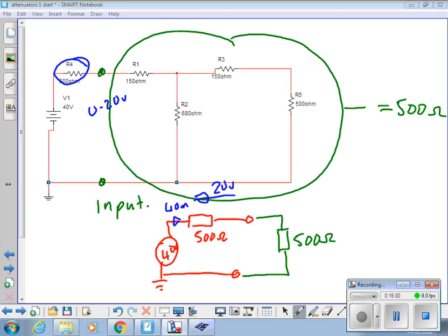So if that was a sensor and I connected it all up, open circuit, at top pressure, I'd get 40 volts out of it. Yeah, because the voltmeter is not going to draw a significant current, and therefore I'd measure 40 volts. But when I connected my 500 ohm to it, then I'd only measure 20 volts.